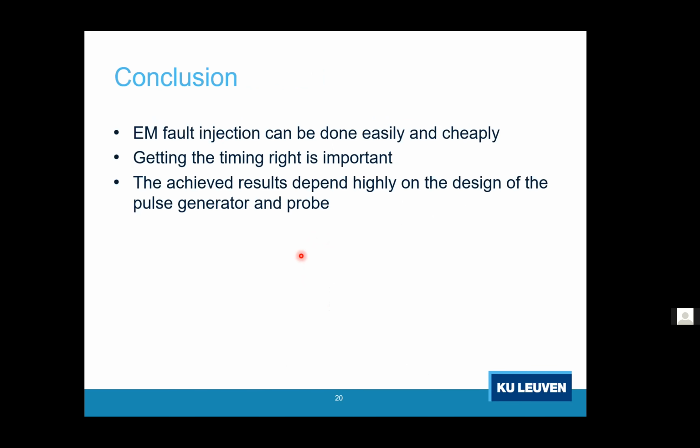To conclude, EM fault injection can be done easily and cheaply, but it's very important to get the timing right, and the results that you get out of it are also highly dependent on how you design your probe and set up your pulse generator.